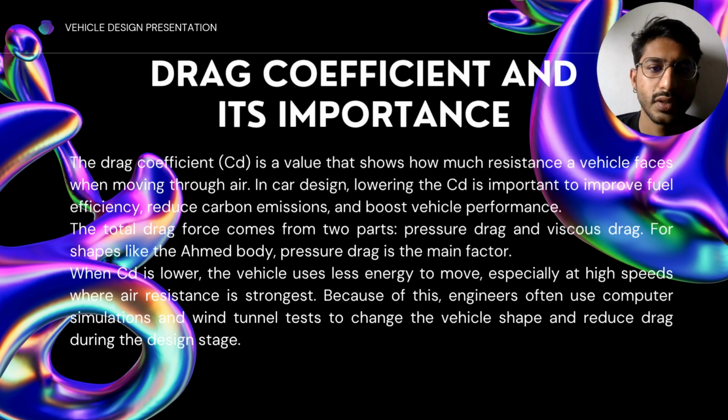Drag coefficient and why it's important. The drag coefficient, CD, is a value that shows how much resistance a vehicle faces when moving through air. In car design, lowering the CD is important to improve fuel efficiency, reduce carbon emissions, and boost vehicle performance. The total drag comes from two parts, pressure drag and viscous drag. For shapes like the Ahmed body, pressure drag is the main factor.